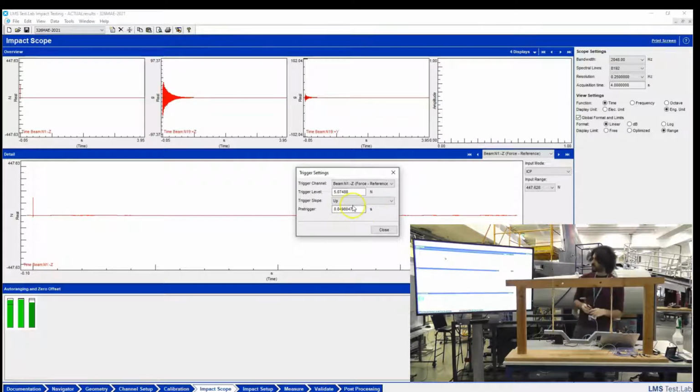When it ramps up, I also set a pre-trigger level, so that the box is continuously recording, and after it senses the trigger, it goes back and records everything from minus 5 milliseconds. No, it's half of a tenth of a second.